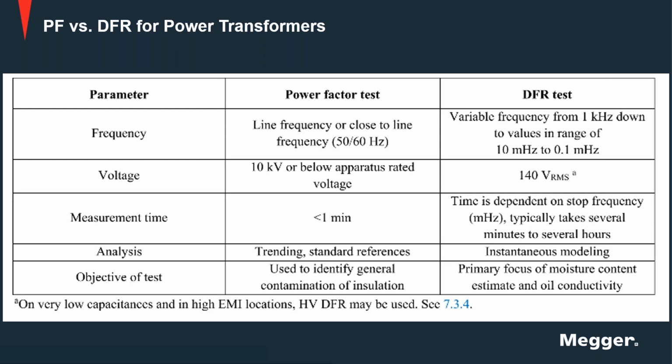You use 10 kV for a 500 kV winding, and you're not stressing that insulation. So the reason for doing a dielectric test is to measure the dielectric properties of that insulation system, which are your power factor, your capacitance, your permittivity. Those are the parameters that you're trying to measure. 10 kV is because you want to overcome any noise that you may have in the substation affecting your measurement. So it's basically an application of signal to noise ratio.